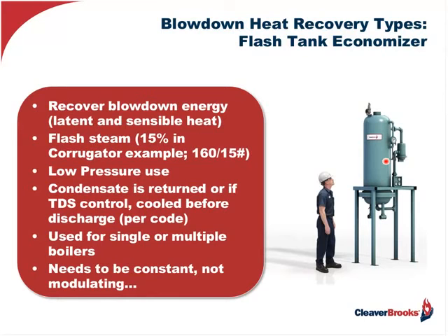It could even be used in the hot plates within that corrugator itself, or for the unit heaters, as I mentioned before, or the deaerator, depending upon the proximity of it to the deaerator. And then that condensate could be captured and used for boiler feed. But again, it's got to be continuous.